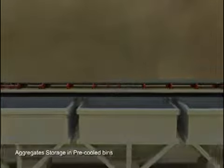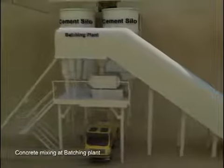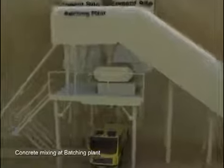Aggregates thus cooled are then carried via a closed conveyor and stored in pre-cooled storage bins. A strike plate mechanism installed over the conveyor directs the aggregates to fall in appropriate storage bins. Aggregates from pre-cooled storage bins are now carried via a closed conveyor to the batching plant weighing mechanism and further for mixing. At the batching plant, aggregates are mixed with cement coming from the cement silos and chilled water in the required proportions to make a concrete mix of the desired consistency. The concrete thus made is transferred into the concrete bucket placed on a truck that carries it to the dam location.